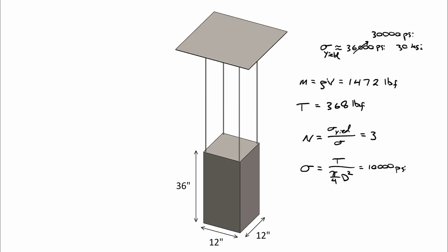It's just part of the fun of engineering calculations, right? In this case, you're spot on. We just reduce the allowable stress by the factor of safety, and that makes everything simpler. So let's go ahead and find that rod diameter.